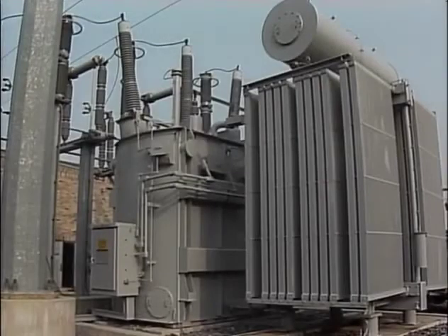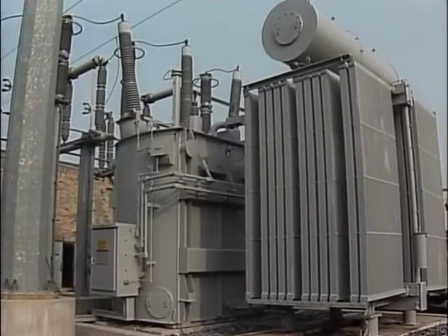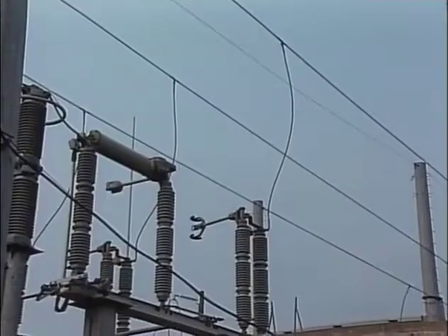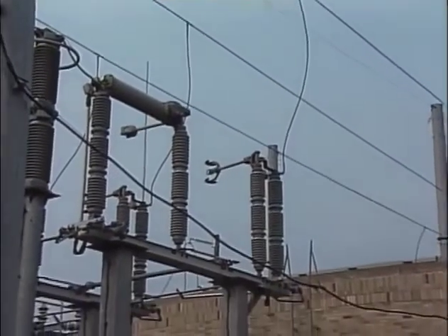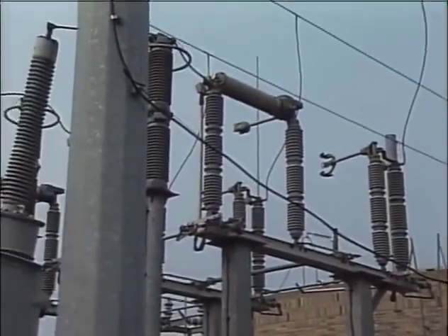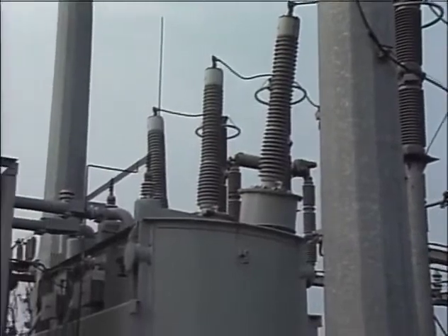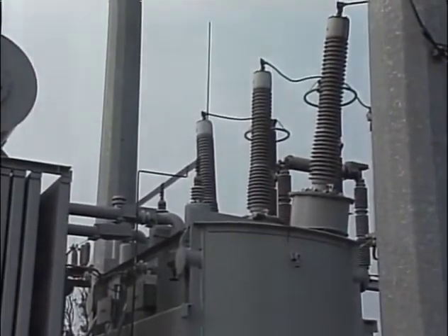There are two basic types of substation shunt reactors. One is oil-insulated. An oil-insulated shunt reactor can look a lot like a substation power transformer. One basic difference between a power transformer and an oil-insulated shunt reactor is that the shunt reactor has three-phase circuit connections to only one set of bushings. The other set of bushings is connected to ground.